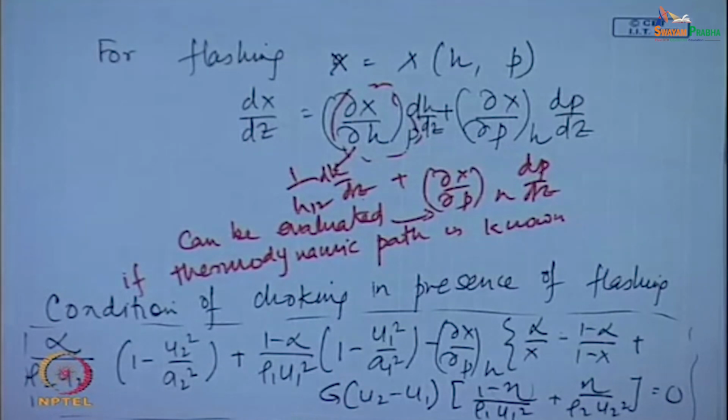Usually from thermodynamic analysis, that is quite an elaborate analysis, probably I will not be going through this, but from that particular analysis people have found out that eta equals half. Usually it is shared half and half by the two phases, but that comes under certain specific assumptions from thermodynamic analysis for isentropic conditions only. For other conditions, it is very difficult to derive eta. Under isentropic conditions for change of phase, we find eta equals half. In other words, this particular force which is required to bring about a phase change is shared equally by the two phases. So, we find that in presence of flashing, the condition of choking is a function of eta,